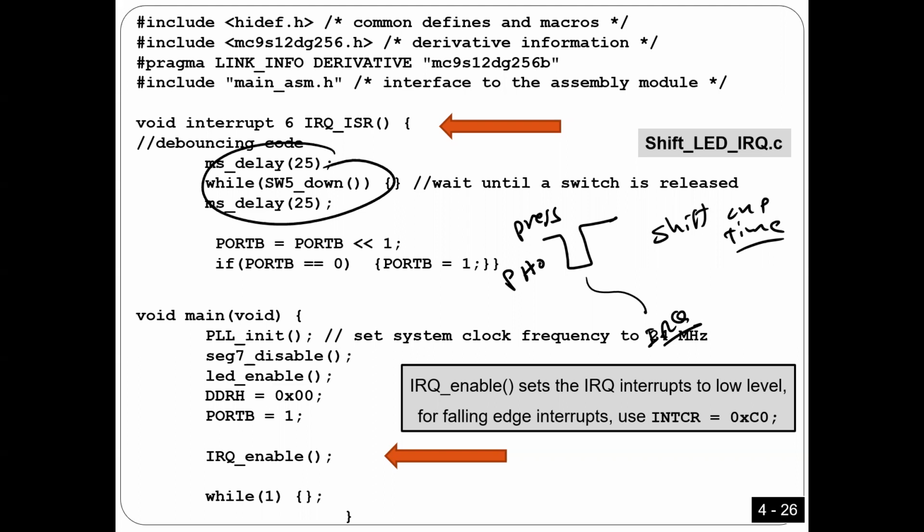Very interesting. So what I'm saying is that that's what you are expecting. Every time I press a button, a signal like this one should be generated. And this one is going to trigger an interrupt only one time because there is only one falling edge, right? And this is going to shift the LED one time. I'm going to show you a video right now. I'm going to show a video with and without this code, okay? To understand what I'm saying right now.